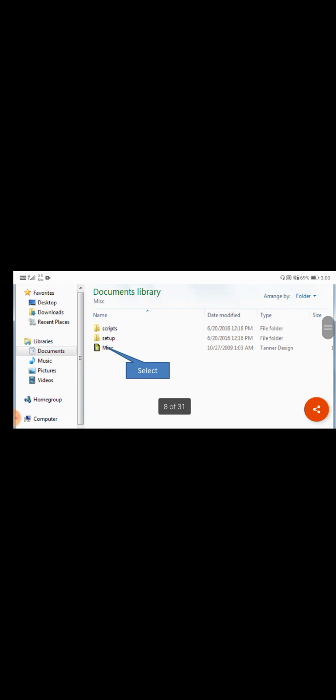After selecting the generic, then you will add MISC, then open view. In the open view, the cell name is cell 0, the view type is schematic, and the interface name keep as it is. Then select OK.